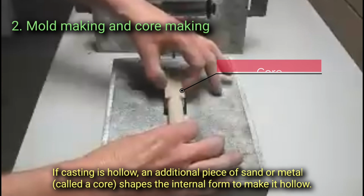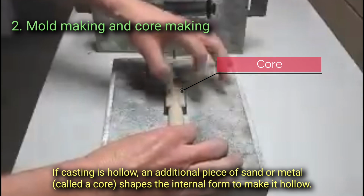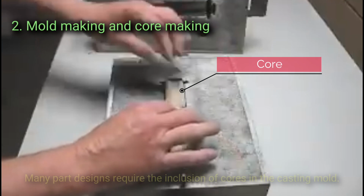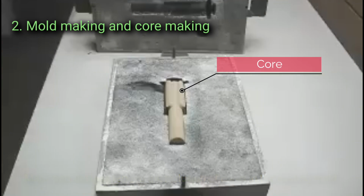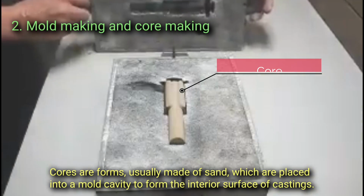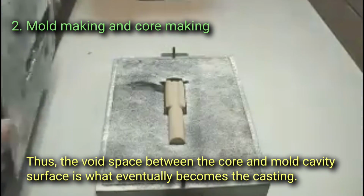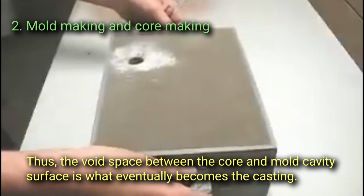If casting is hollow, an additional piece of sand or metal, called a core, shapes the internal form to make it hollow. Many part designs require the inclusion of cores in the casting mold. Cores are forms, usually made of sand, which are placed into a mold cavity to form the interior surface of castings. Thus, the void space between the core and mold cavity surface is what eventually becomes the casting.